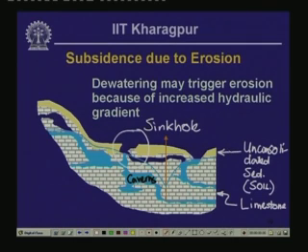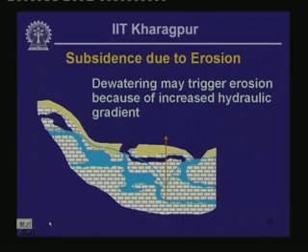Now sinkholes typically develop in a much more rapid sequence than the settlement that soft soils undergo because of lowering of groundwater table. So if you have got a structure within the area affected by development of sinkhole, the structure can collapse, and it could cause a lot of damage to property and life. So this is another way lowering of groundwater table can cause problems to constructed facilities.